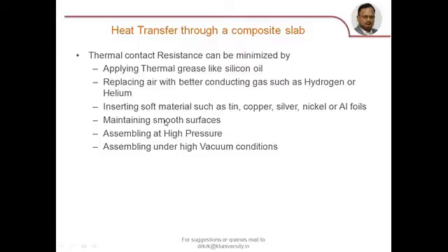Inserting soft materials between the two parent materials such as tin, copper, silver, nickel or aluminum foils, so that the white space is filled with these better thermal conducting materials, and maintaining smooth surfaces so that the gap will be minimum and thickness of the film becomes very small. So when the thickness of the film is small, the resistance also becomes small.